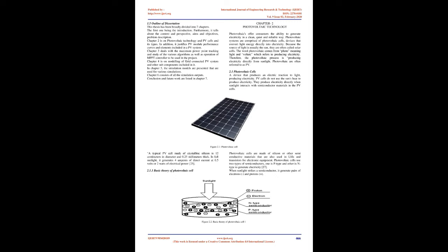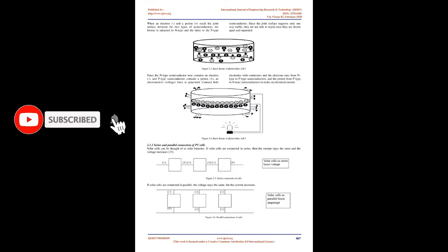B. Marion, J. Adelstein, K. Boyle and Fellows [9] presented a paper about performance parameters for grid-connected PV systems. Three performance parameters may be used to define the performance of grid-connected PV systems: final PV system yield YF, reference yield YR, and performance ratio PR. The YF and PR are determined using the nameplate DC power rating. The YF is the primary measure of performance and is expressed in units of kilowatt-hour/kW. It provides a relative measure of the energy produced and permits comparisons of PV systems of different size, design, or technology.